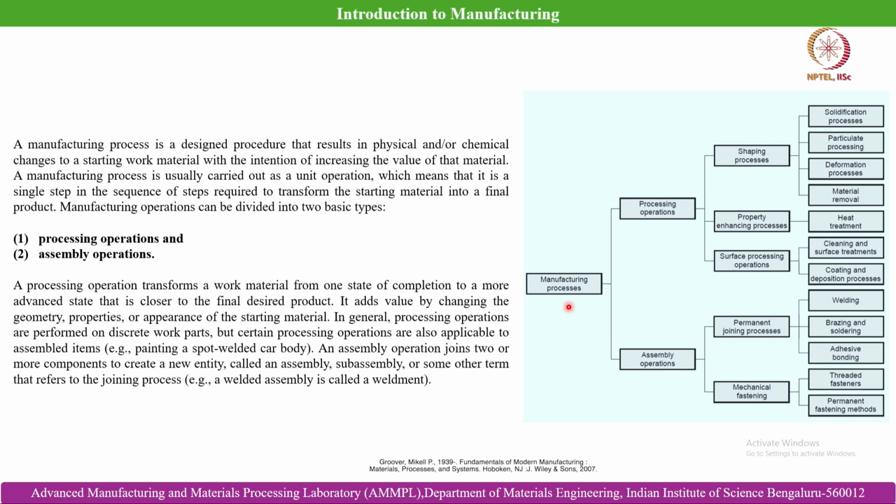These are the techniques where we can get the component directly from the manufacturing process. The secondary processes, for example machining and forming, work with already processed preforms, which we need to rework so that we can achieve the final desired dimensions of the part.